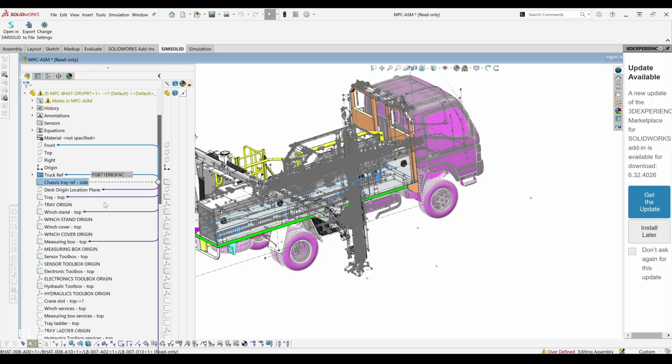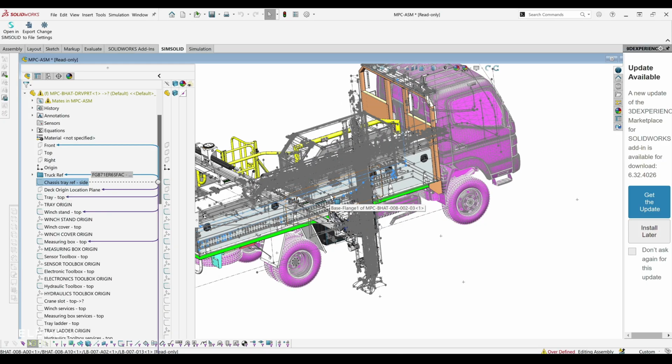Whereas when you're in CAD, you're structuring a model in a way that is, first of all, manufacturable, which means that you need to have reference planes or whatever. Parametric 3D modeling is the key to doing really good CAD in our experience. So having sketches in this way, where one sketch references the features of another sketch, is the way we've found that SOLIDWORKS works really, really well.